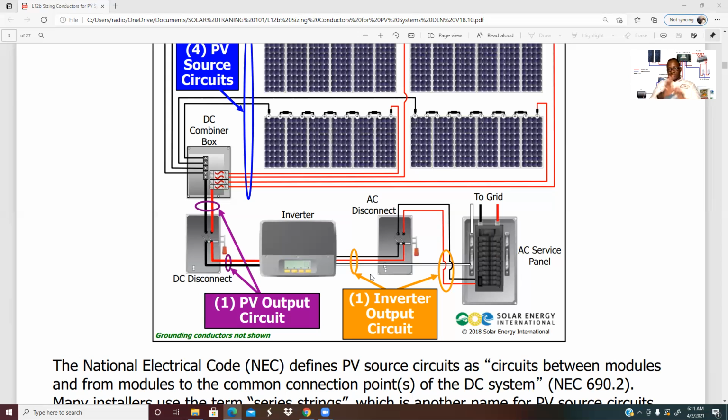It's not a battery-based system. This is a grid direct design right here, just to let you know, which can also be used if you have a generator, where you can have a second input of AC current coming into the home as well. If you have a generator, this is a beautiful setup. That's why you don't see a charge controller, you only see an inverter.